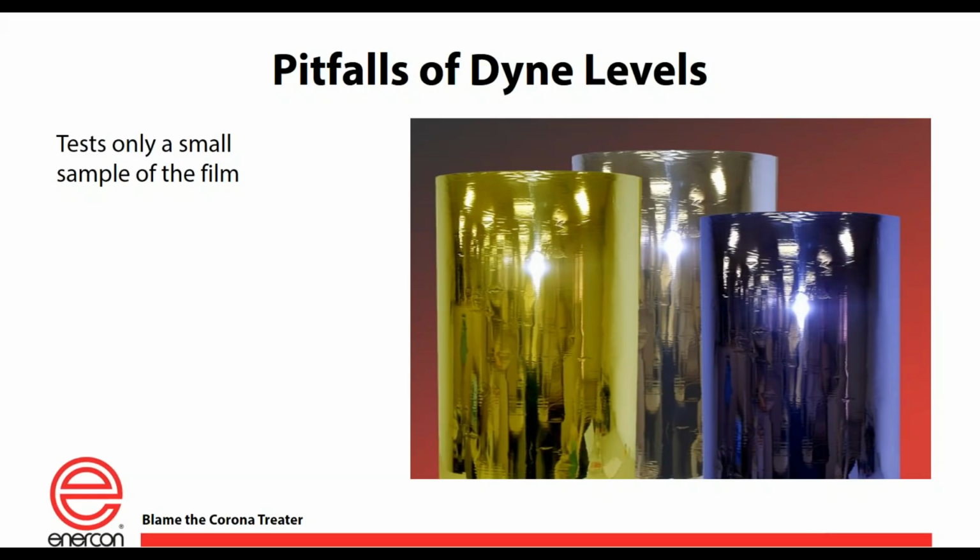Secondarily, when you talk about those contact angle devices, they are very accurate, but they are only measuring like 1 square inch of the material. All of us out there know that in the real world, we're dealing with 5 foot wide, 6, 7, 8 foot wide webs. So it doesn't matter if a 1 inch square area looks good. You need to know how it looks across the web width. And so those devices really aren't suitable to tell you that. Doing a Meyer rod test on that material, because you can spread the solution out over a wide width, is much better, and you're able to actually ascertain something.